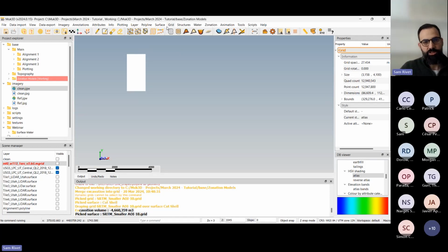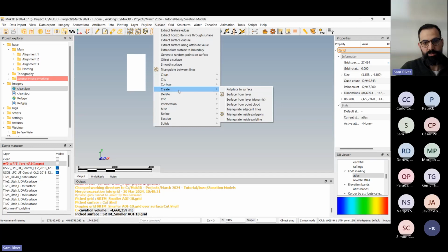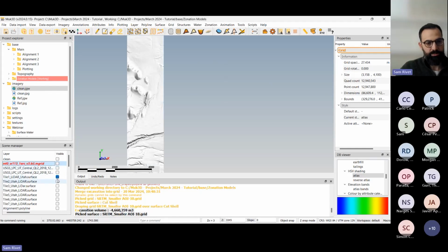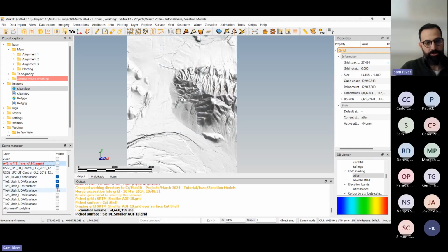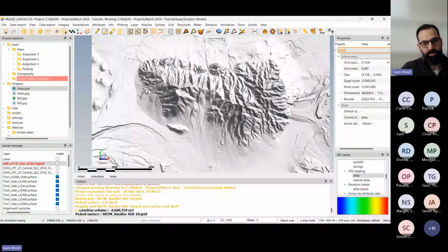And then you can just take these directly and build a surface out of them. Just go to surface, create surface from point cloud. And as you can see here, I did that for a number of tiles and recreated the entire area with that LiDAR data. And you can even see, in plan view from here, a little bit of a difference in the quality of this versus the SRTM data.